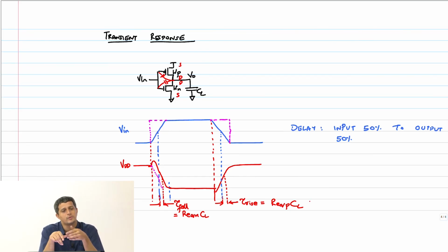So now if you ask me, is that 0.693 necessary? Well, honestly, in both inverter A and inverter B, if I drop the 0.693, it doesn't matter. I am only looking at telling you which one is faster, and even the 30% faster will still hold if I drop the 0.693, right? Keep that in mind for all the derivations that we are doing throughout this. Ultimately, you have to resort to simulation for accurate estimates. No choice there. Okay.